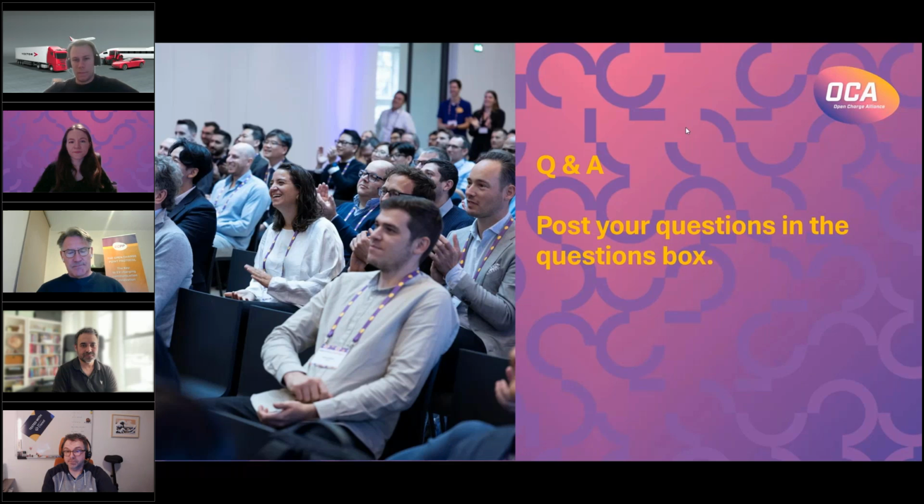And I agree, Jacob. It's a new functionality. If you're just asking for can we get 2.1, and you don't need the new functionality, probably nothing happens. But if you need it for credit card payments, you need authorization of transaction limits. If you need bidirectional charging, if you need any of the new functionality, you will need to migrate. You will need your supplier to migrate your chargers to 2.1.